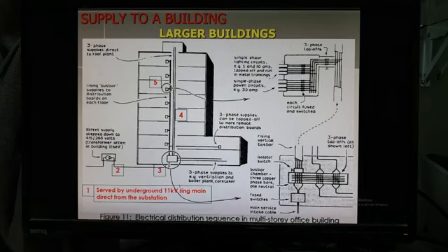So from the three phase here, they would switch into single phase, where each of these connections will connect one live and one neutral. This is one live, one neutral, one live, one neutral. So it is single phase. Single phase for lighting circuits, 5 or 10 amps.